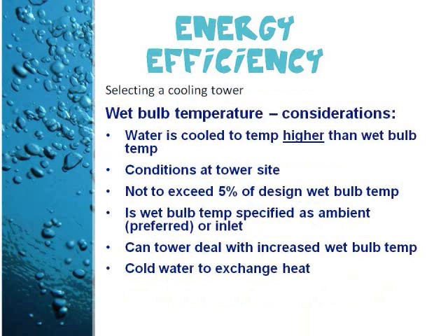In the selection of cooling tower, we must also consider the wet bulb temperature. Wet bulb temperature is an important factor in performance of evaporative water cooling equipment because it is the lowest temperature to which water can be cooled. For this reason, the wet bulb temperature of the air entering the cooling tower determines the minimum operating temperature level throughout the plant, process, or system.